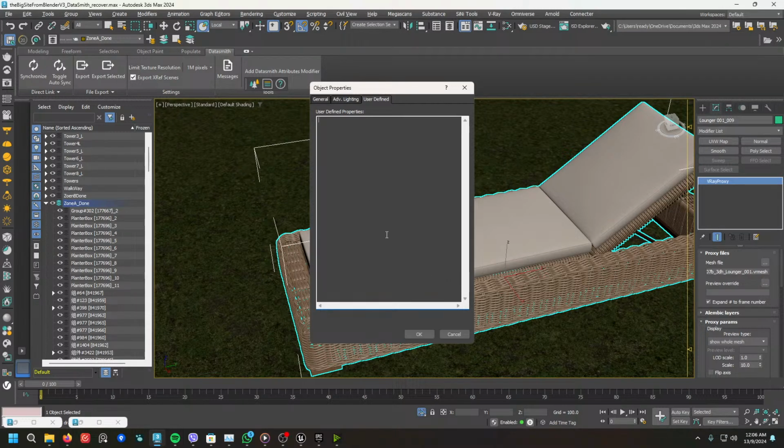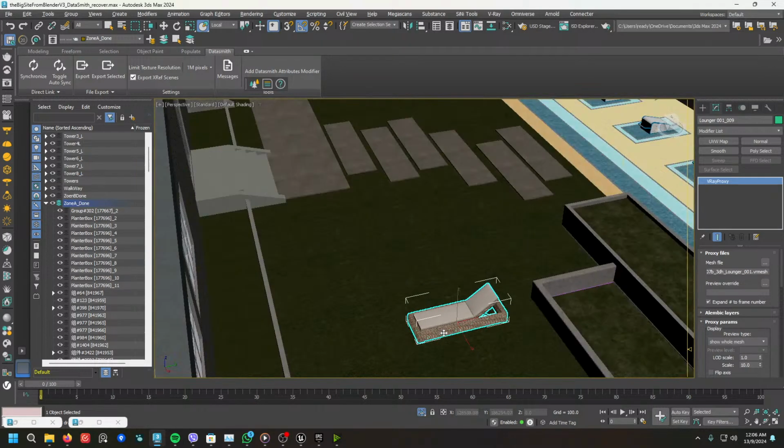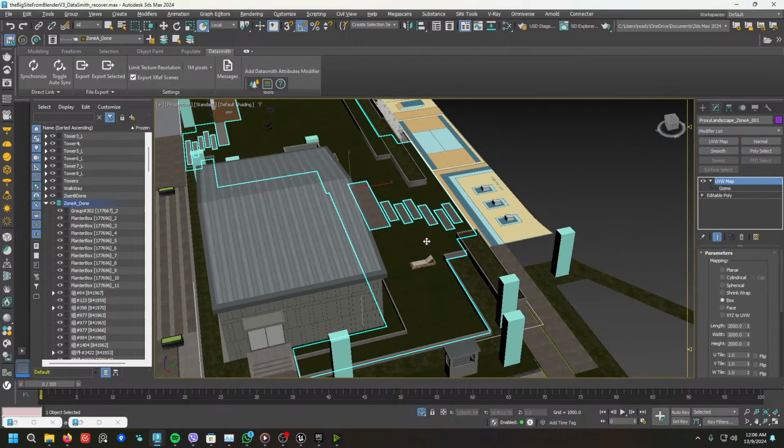Let's say this is a heavy mesh, right? And when you import it inside Unreal Engine, it will detect a certain value or certain key inside your file, and it will convert automatically to Nanite. Yeah. So let's say I write nanite here and equal true, okay, and I use this value later inside Datasmith Data Prep, so we detect it and convert automatically. Okay. So this is one thing.